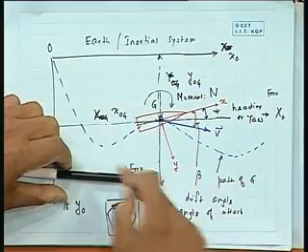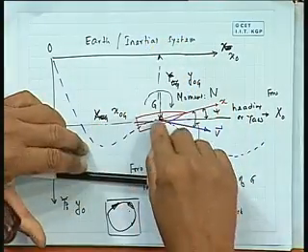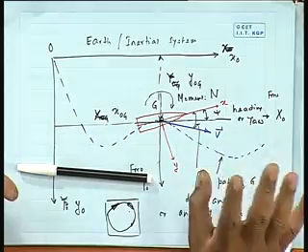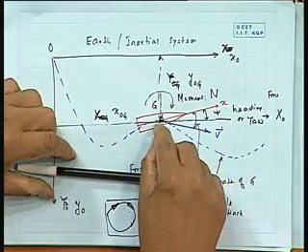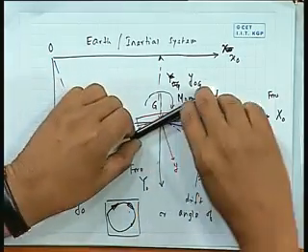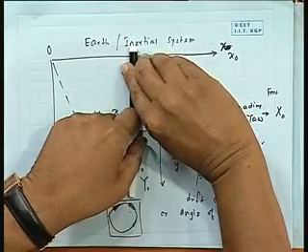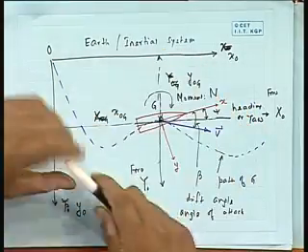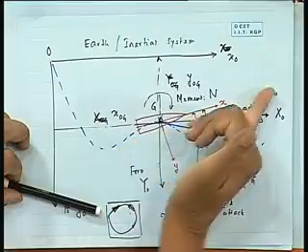It depends on the geometry for a particular hull, but for a given hull it will not depend on geometry anymore if you define the forces along the body system, because the body geometry along this Gxy is not changing with time, whereas the body geometry about the earth axes is changing: today it is like that, tomorrow it is like this. Therefore, it would be much easier to define all the parameters and the equations of motion along this line.